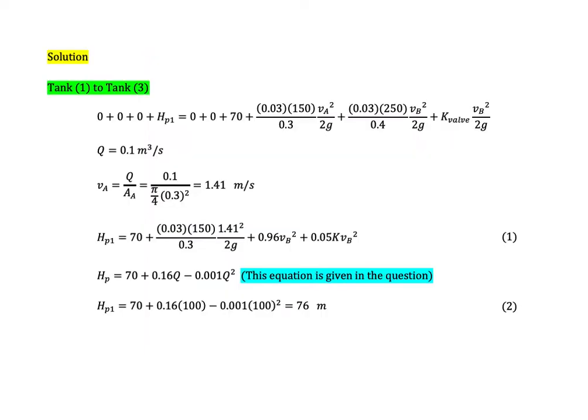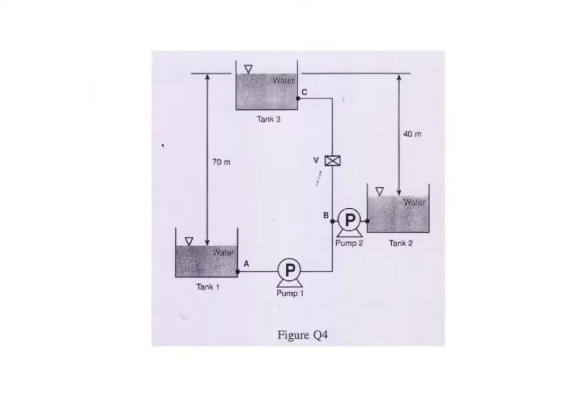And then in this calculation, I hope you could really understand that when we want to calculate the major losses, we must make sure that the friction coefficient and the velocity are the same. So according to this diagram, we only have one pump here, so we have a velocity of VA.